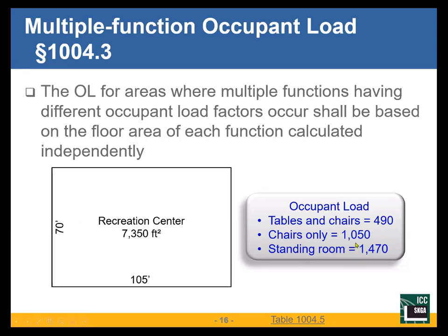If I take standing room only and design my exiting system to handle that occupant load, we've already covered these. We don't have to worry about it. We've already made it. If I can handle that, I can handle less than that.